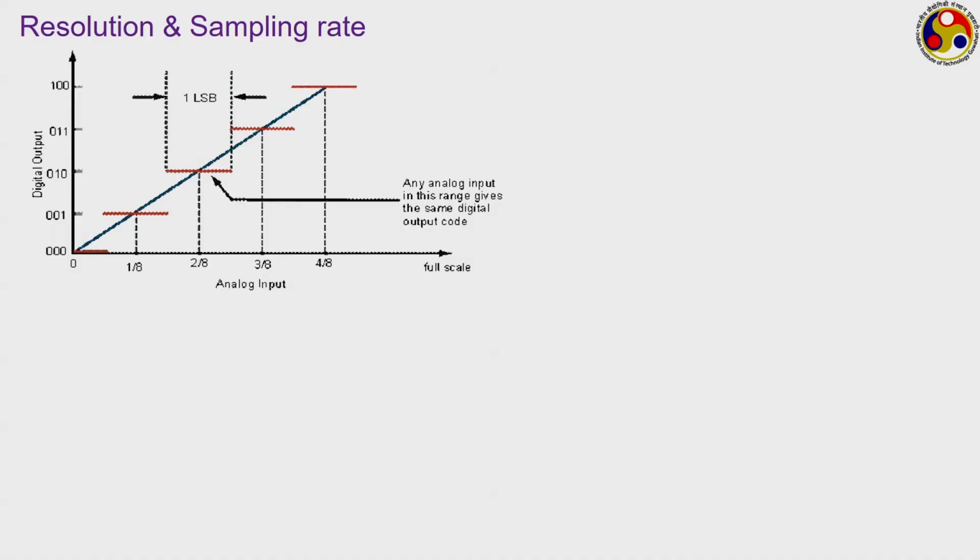So this is again just repeating the same: the resolution, any value appearing within this signal range will be given the same digital level, and that will continue for each of the digital levels. The only option is to increase the resolution of the instrument, and that is to allow more number of states within the range of voltage that you are dealing with.